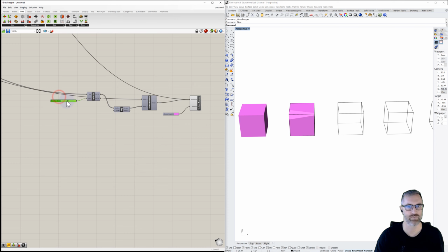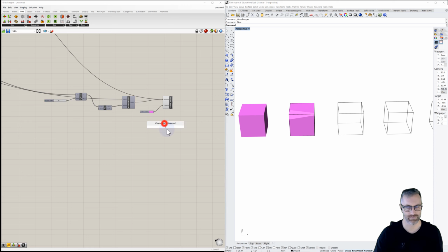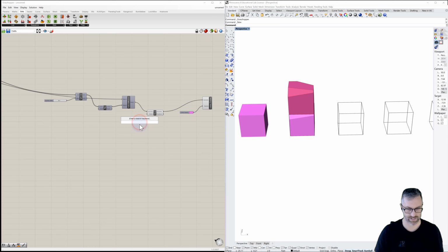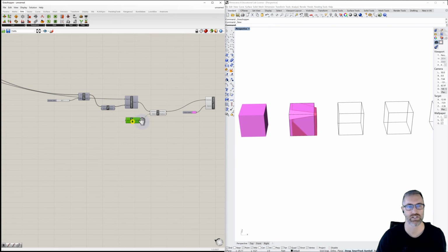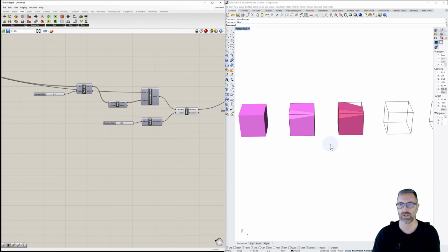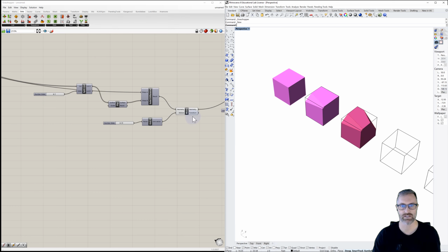We know this is set to number 2, but let's also move this over. So we have to do the move before we do the representation. Here's the result, the geometry, and we're going to move it in the X direction. We know it'll be positive, and it's going to be 20. So we can just do that for the slider, plug that in. So now we get the first and the second